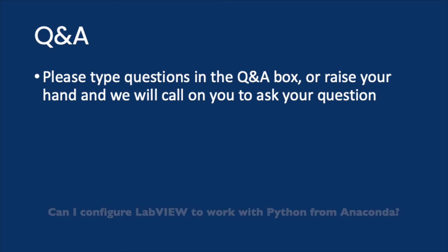So moving on to the next question, can I configure LabVIEW to work with Python from Anaconda? Yep, I can take that one. So we don't have direct integration with Anaconda, but you can configure the path to point the Python command to Anaconda.